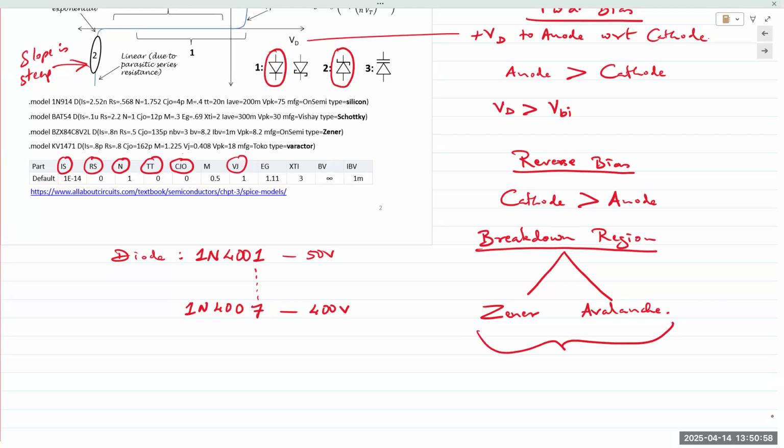So far, so good. There's a lot of information. All right, now let's talk about the two mechanisms, Zener and avalanche. Zener mechanism occurs specifically due to the heavy doping that is done to the p-n junctions. Okay, so for Zener breakdown to occur, there must be a high number of charge carriers than in a regular silicon diode. And so when you apply reverse bias, it does not take much energy for the minority carriers to actually cross over the junction. Okay, the sheer number of dopant atoms cause a large number of electrons and holes to appear in that p-n junction diode.